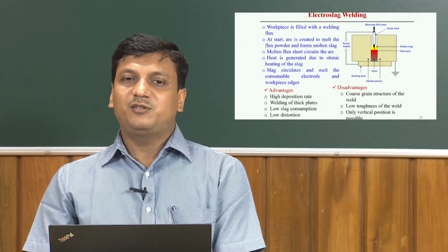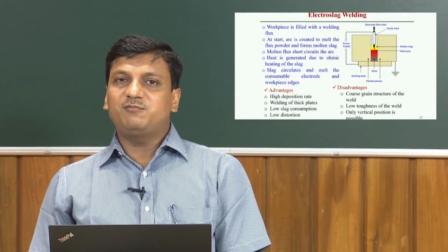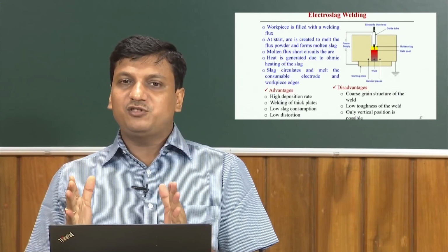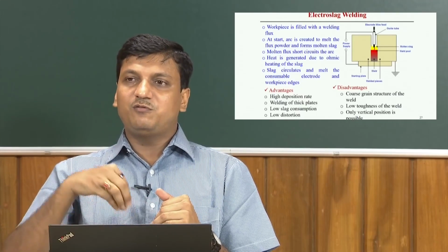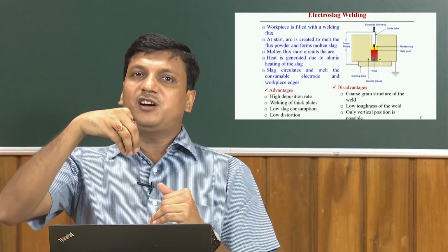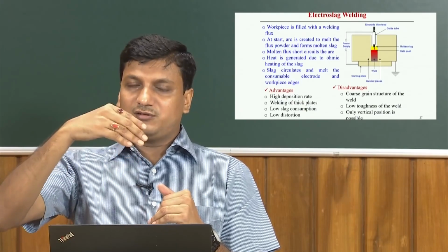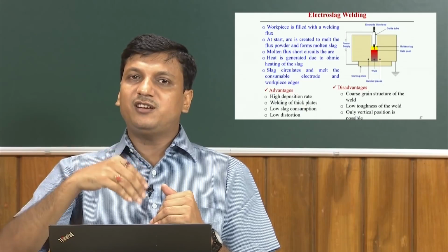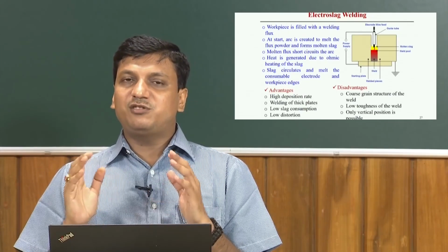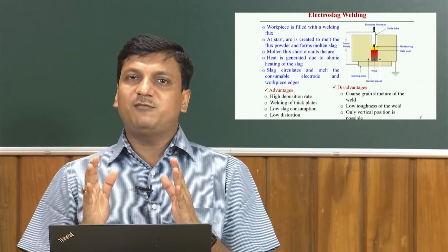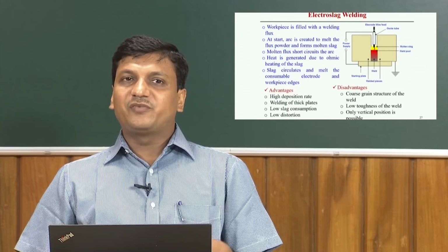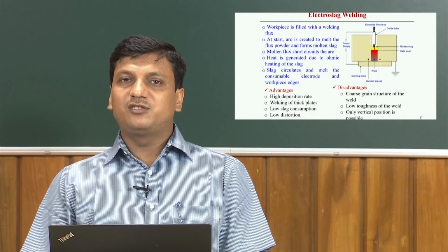When you keep two plates vertical, you start welding from the bottom plate, and the electrode keeps moving in the upward direction, and consequently it makes the weld in the back side. So, this process is specifically advantageous for joining two vertical plates on a large scale, that means when a large volume of molten pool is required. In this case, this process is more suitable.